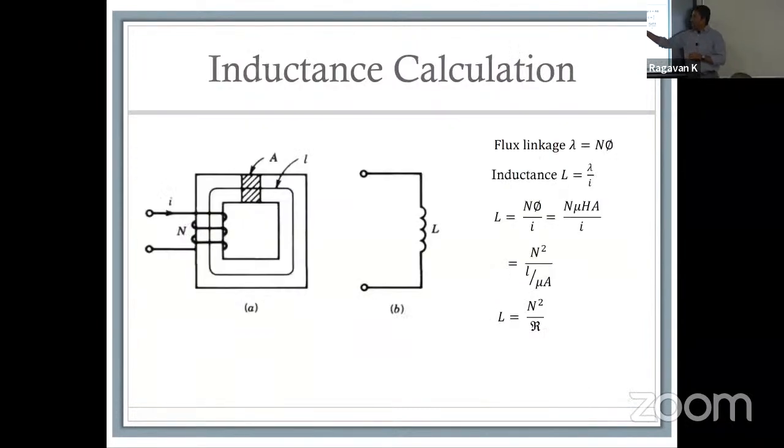If you look at a coil, you end up with a calculation for inductance, which means now your number of turns has a direct relevance to what inductance you're going to get. This is very important for motors like switched reluctance machines, where the number of turns has a significant impact on the inductance you're going to get.